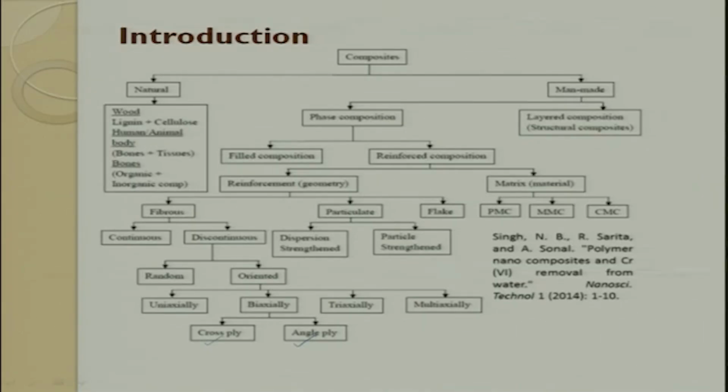So, on top of it, to reduce the temperature, why can't I use a lot of coolant? Coolant, MQL you can try, that is minimum quantity lubricant, or you can do flood, you can do spray, whatever you want to do, you do. But you should have at the back of your mind, polymer is hygroscopic in nature. The moment it is hygroscopic in nature, the polymer is going to attract the OH. The moment there is OH present for a certain duration of time, this will try to weaken the matrix.